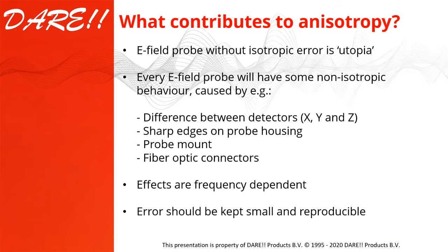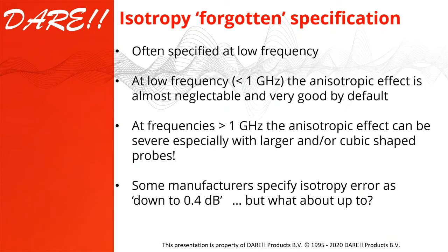All these effects are also quite frequency dependent. You will see in the later slide that at lower frequency, it's all relatively fine. But the higher you go in frequency, the more the problems start to increase. And in general, you must say that the field probe should have as low an isotropic error as possible. And it should also be reproducible, of course.